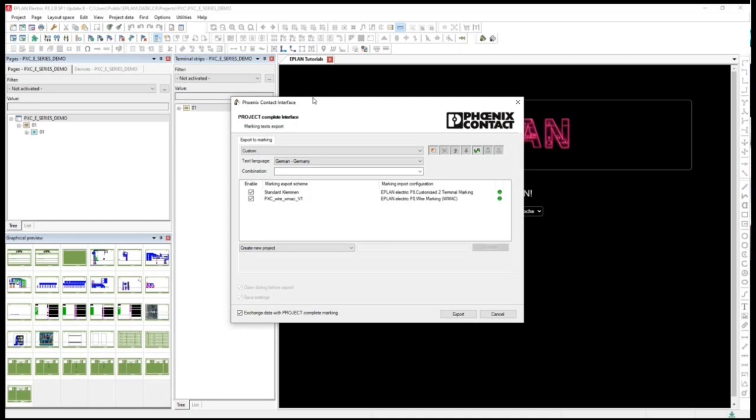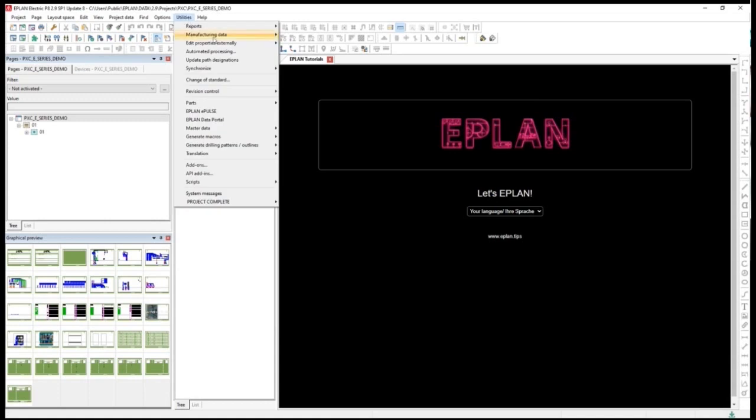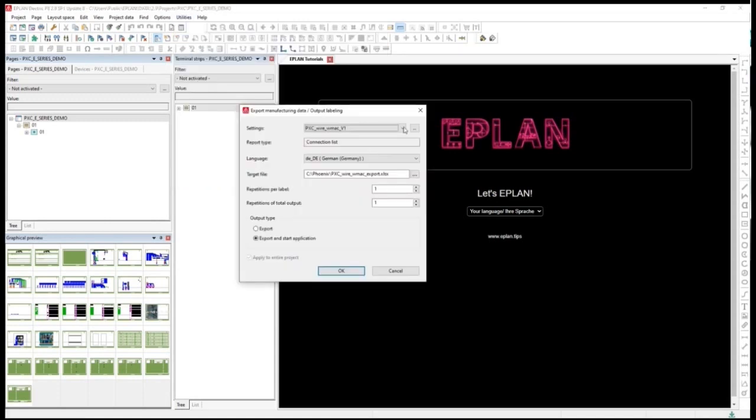In Eplan you also have to adjust this: this is the main terminal block, this is level 1, level 2, and this information will also be exported to planning. In planning you can then really see the terminal strip, how it looks, and you can export this information to marking. I have a new scheme that is already in progress right now. I can show you, because in the old scheme it was not really possible to adjust the levels and also the marking material.